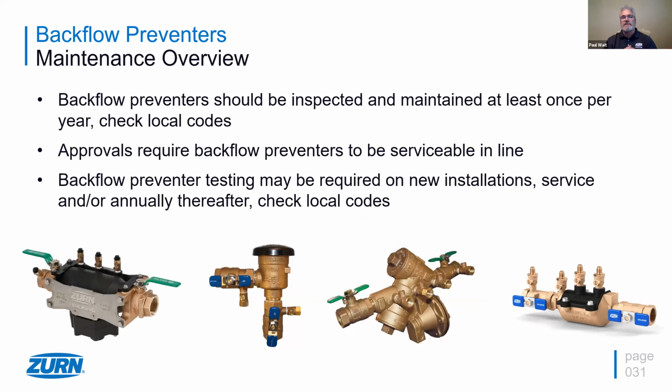Maintenance. So backflow preventers, they need to be inspected and maintained at least once per year, but local codes are going to tell you what to do on what type of backflow preventer. One of the things we see specifically with pressure vacuum breakers is once they're installed, a lot of times, especially on a residential system, people are like, all right, I don't have to touch it again. And the water purveyor's like, yeah, it's just a house, don't worry about it. And so there's a lot of non-compliance going on, and it's being wink, wink, forget about it. And that is kind of a concerning thing.